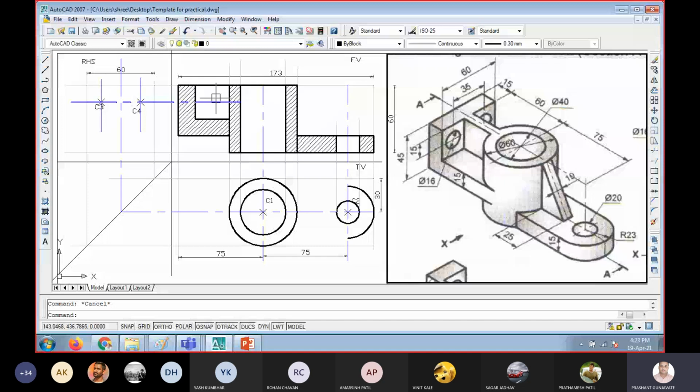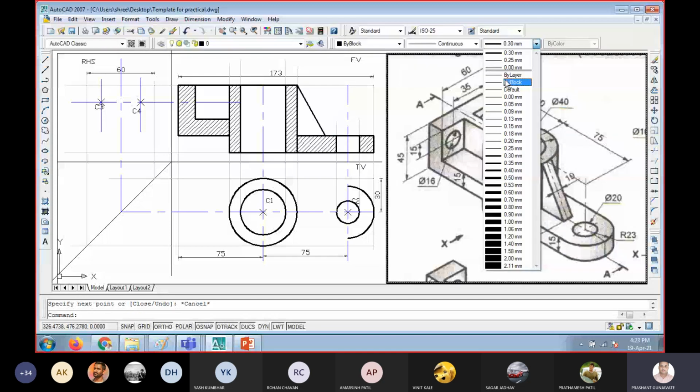So the rib has, if you see the dimension in the question figure, 25 mm. So from this end it is 25 mm, and it is up to this. So I will project this thing in top view, then it will be okay. Now I will show the dimension between these two. Okay, so now it is okay. So this is how the front view will look.